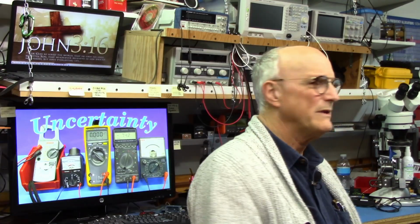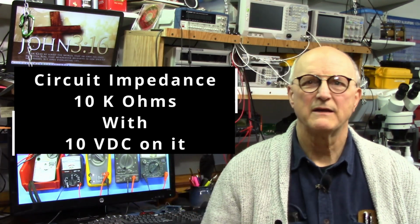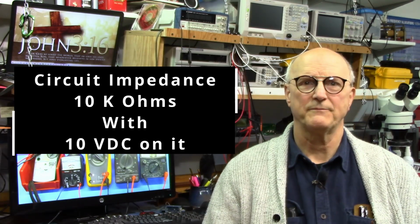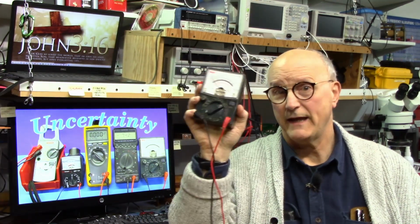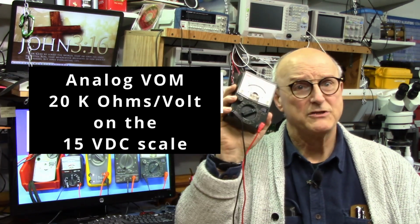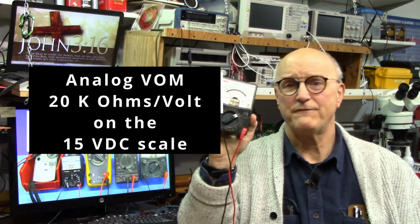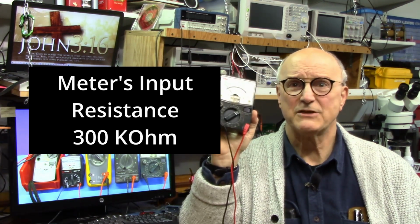Now, you might ask, why is the input impedance of my measurement device even an issue? Well, let's consider a medium impedance circuit, let's say like 10 k ohms, which has 10 volts on it. Now, this isn't especially a high impedance, but it certainly isn't low either. Now, we take my old analog multimeter with its very respectable 20 k ohms per volt rating, and to measure the 10 volts, I have to use the 15 volt scale. This means that the input resistance of the meter is going to be 300 k ohms, and that sounds pretty respectable.